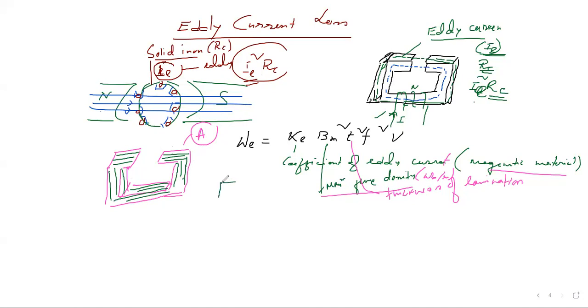The structure is like that. This is a single lamination. So instead of a solid iron bar, we use that laminated iron core. This is basically called a lamination, which is why it is mentioned that T is the thickness of the lamination. If you use a laminated iron core instead of a solid iron core, the effective cross-section area is reduced.